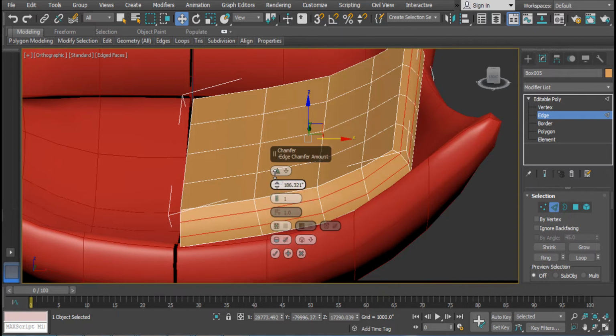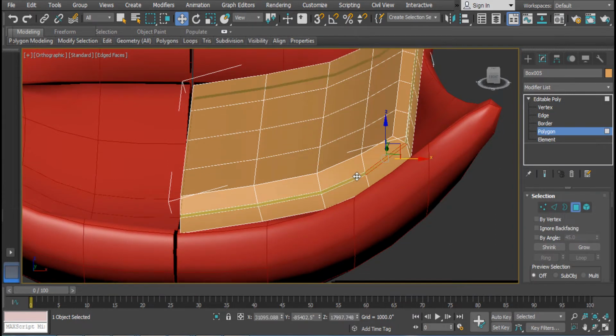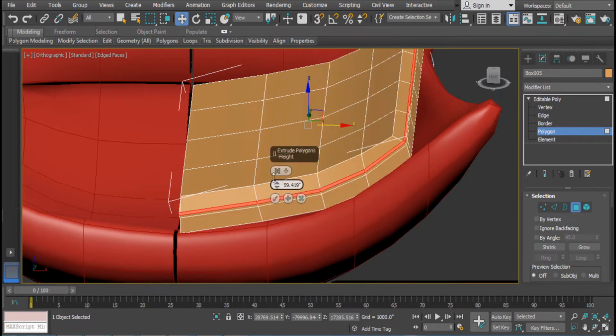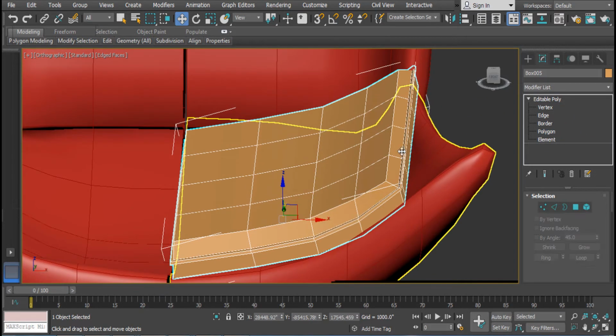And with this similar technique, here is how to make a smooth shape on the edge of any kind of shape you made in a box. For that, you need to click on the surrounding edges first. Then there is an option called chamfer. That is the best option to turn a sharp edge into a smooth edge, or to create smooth lines on the edge.